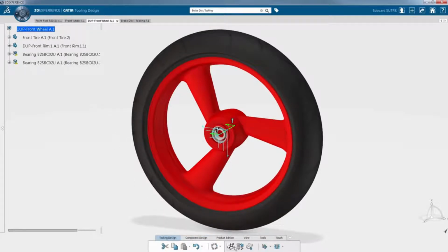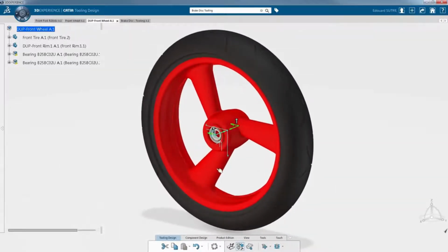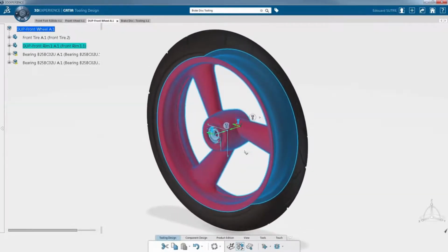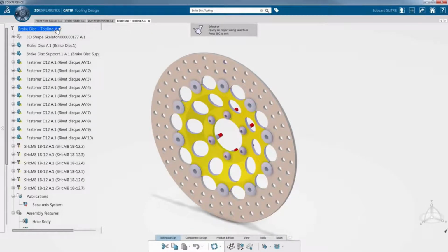We insert the brake disc assembly in the front wheel product using the component placement command. Select the receiving part, the red rim in this case, the interface to populate, two possible anchors are available, and the component to insert from your current session or search results.